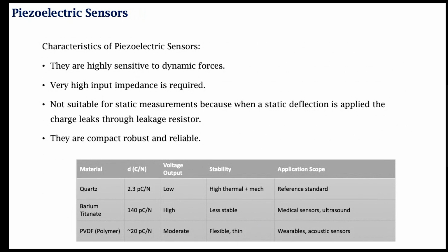In this case, the piezoelectric transducers emit 5 to 10 megahertz bursts, and the Doppler shift that is produced yields velocity after compensating for any changes in angles.